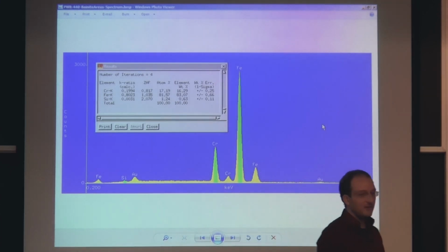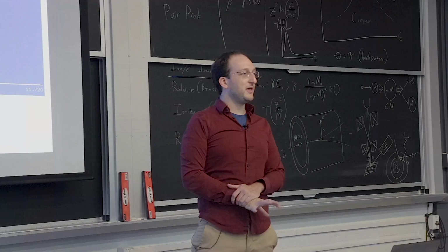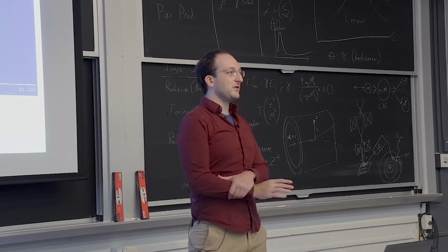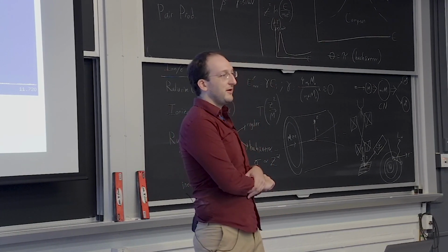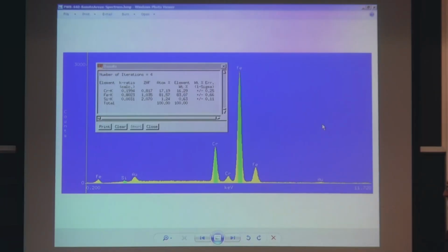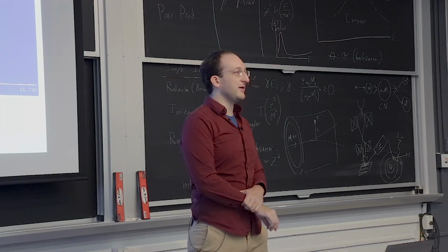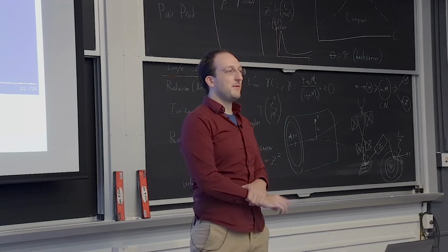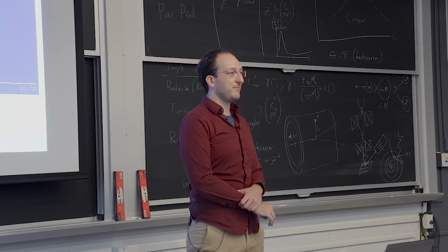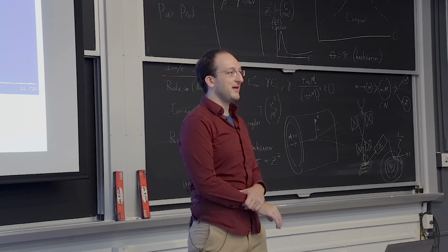Gold's kind of an interesting one. There's two things about doing analysis with gold. A lot of times you have to coat your materials in gold to boost their secondary electron contrast. But also gold's, I think it's its L line, or M line, I forget which one, is the same as argon's K line. And we have an expression in the electron microscopy world: the probability of finding argon in your sample decreases with experience. Take a second to parse that.